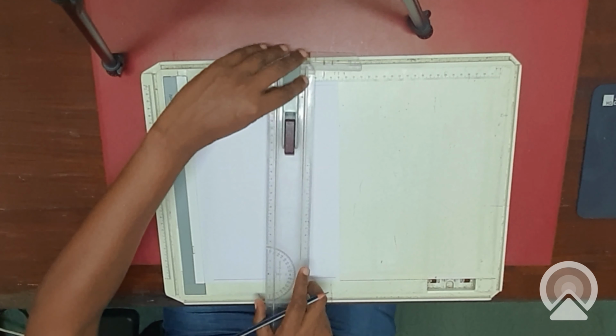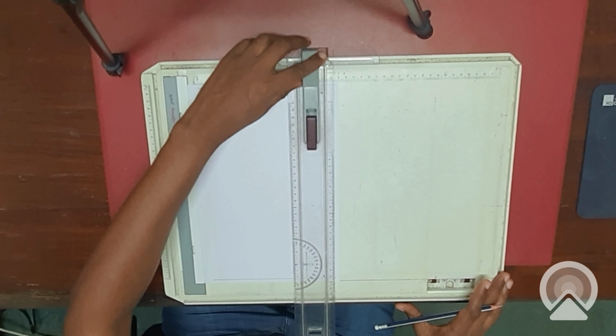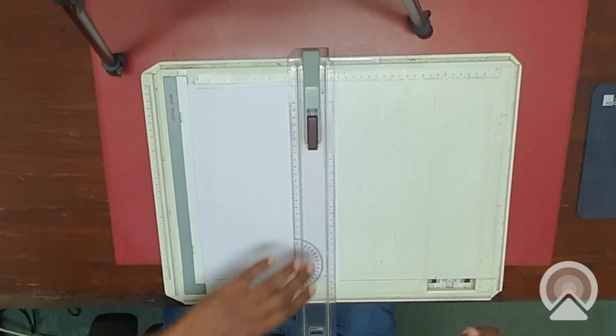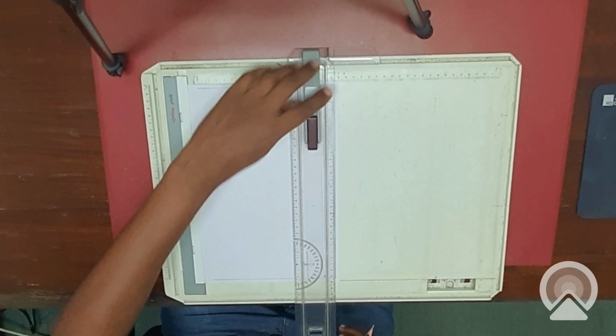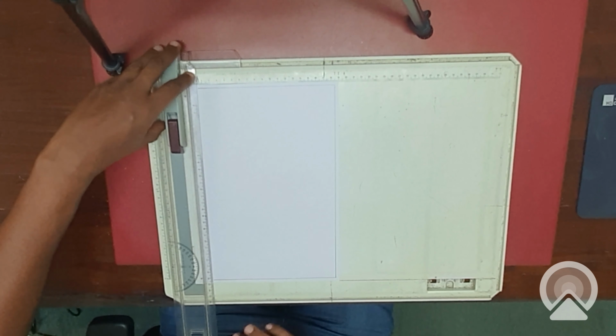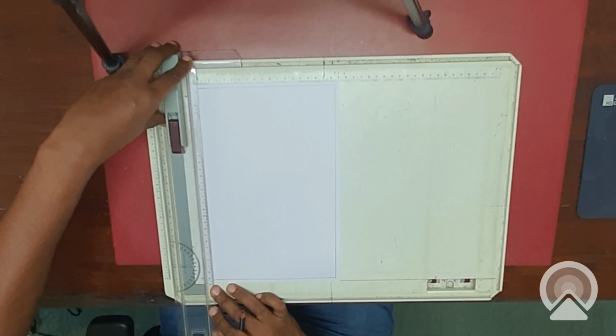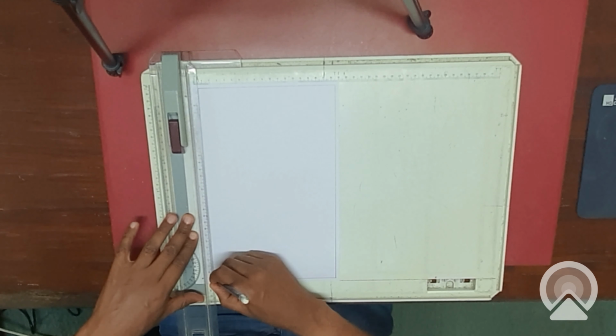So here. Now you can rotate your T ruler so that you can draw the vertical margin. Make sure the T ruler is within the groove, and then you can locate here the end of these two lines, and then you can draw the vertical margin. You do the same for the left-hand side margin, the filing margin. So you just join these two lines this way. And that's it about the margins.